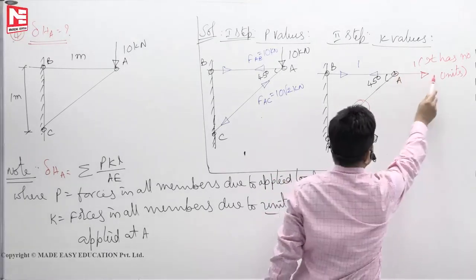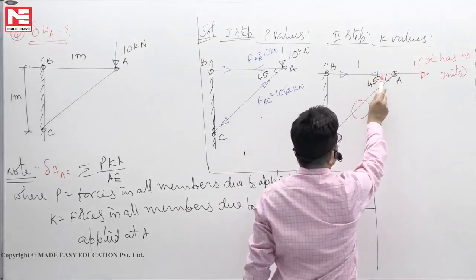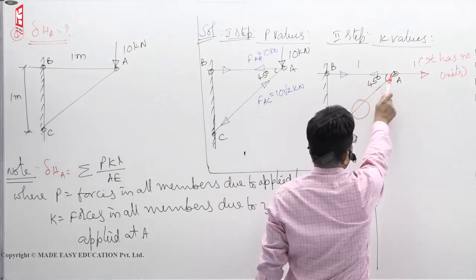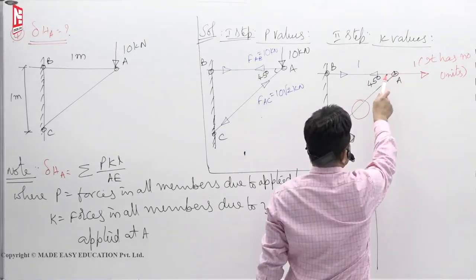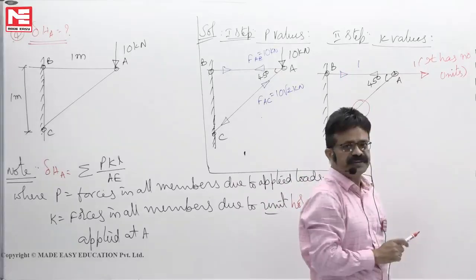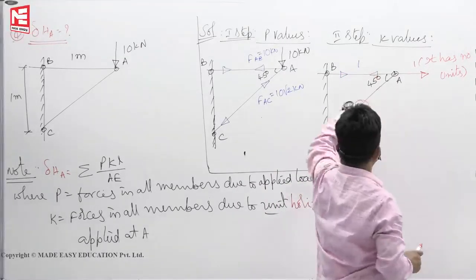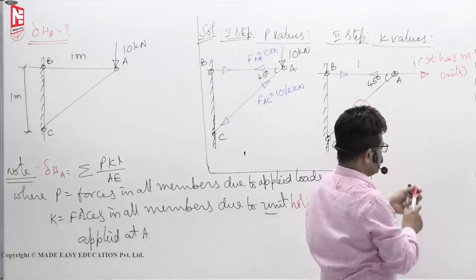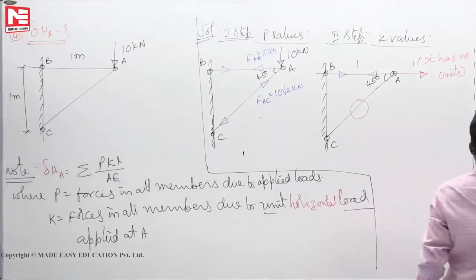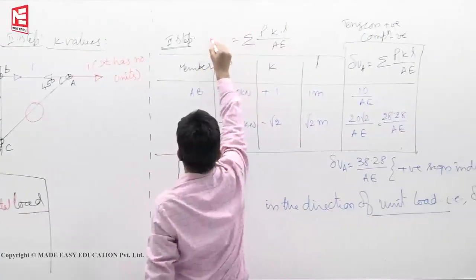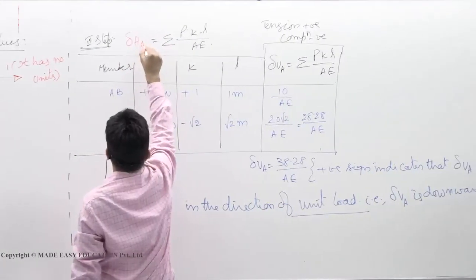Next here, one right side, to balance it, it should be left. First you have to put like that. Put arrow mark left, right 1. Next, now this arrow is away from the joint. Here also arrow must be away from the joint. Okay, so this K1 will not change, but the other will become 0 for the horizontal displacement. This is one change. Then third step, delta VA, now you replace it by delta horizontal displacement at A.